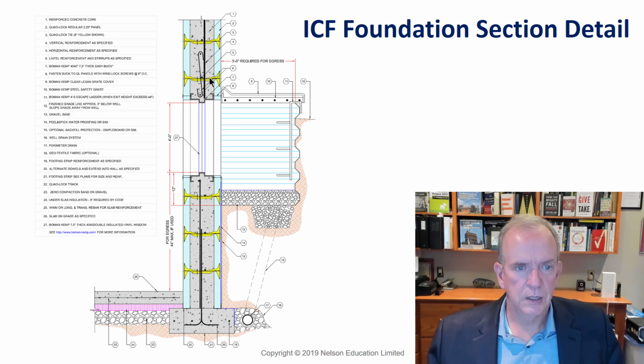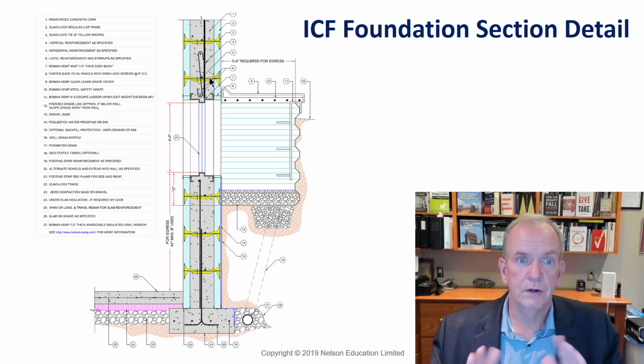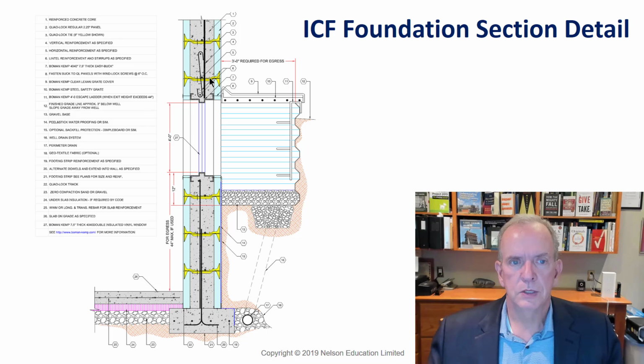That was very interesting. The real skill is just making sure that you properly brace it, because it is very flexible. So you've got to make sure whatever the manufacturer's requirements are, you follow them to the letter and then some. But if you've got that, then it's great, because it is going to be a very solid wall. It's going to be a reinforced foundation wall.